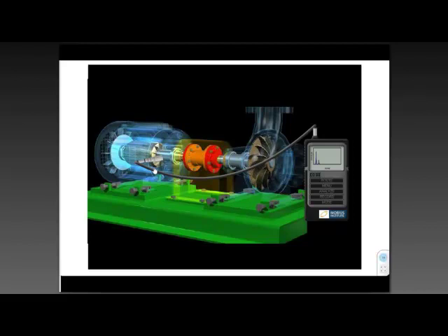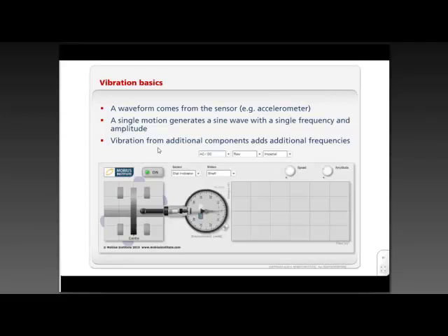But we need to test each of the bearings because the vibration, particularly high frequency vibration, which I'll mention in just a moment, doesn't necessarily travel from those bearings along the shaft to those bearings. So that's basically what we need to do. We should measure the vibration in multiple axes, if at all possible, which includes axial as well. And we need to monitor as many bearings as we can to really make sure we are detecting all the problems that are going on.